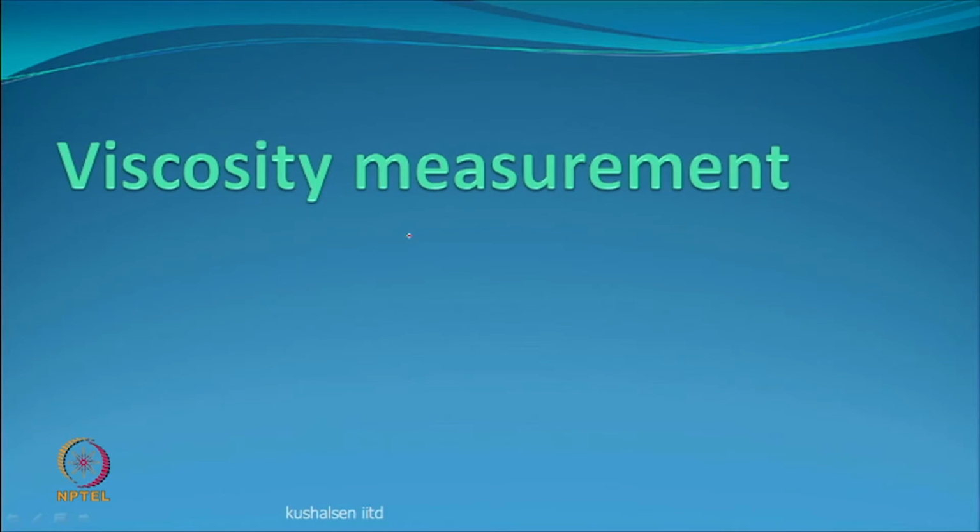It is like when you talk about the crystallinity of a polymer, you say how did you measure? Say I used a wide angle X-ray diffractometer, very good. Another one can say I used a DSC to measure the crystallinity, or density to measure crystallinity. You have to say this is density crystallinity, this is X-ray crystallinity, and this is the other method that we use.